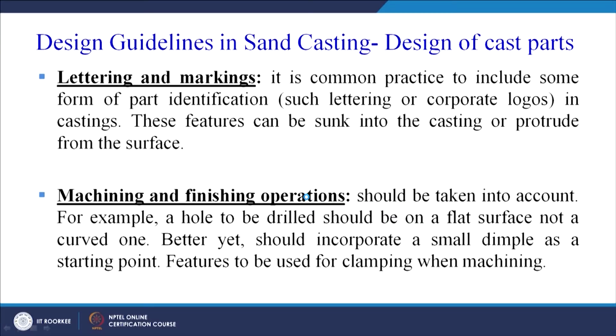It is a common practice to include some form of part identification, such as some letters or the corporate logos in the casting. These features can be sunk into the casting or protrude from the surface. So when we are designing a product which is to be made by casting, we can make some letters which can be either sunk into the depressions, made as a writing on the sand, or they can be protruding out or embossed on the surface.